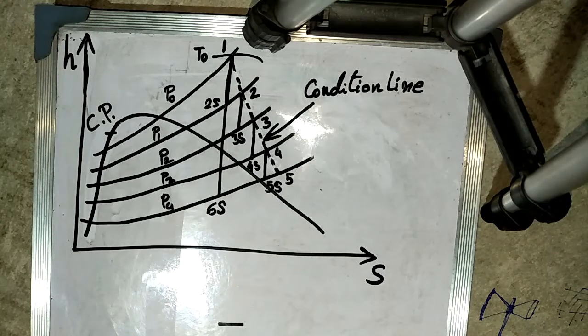Third, the constant pressure lines diverge from one to another, thereby increasing the enthalpy drop for the same pressure drop. Because of conclusions number 2 and number 3, the sum of available energies, that is the isentropic enthalpy drop for each stage, is greater than the available energy, that is the isentropic enthalpy drop for the whole turbine.